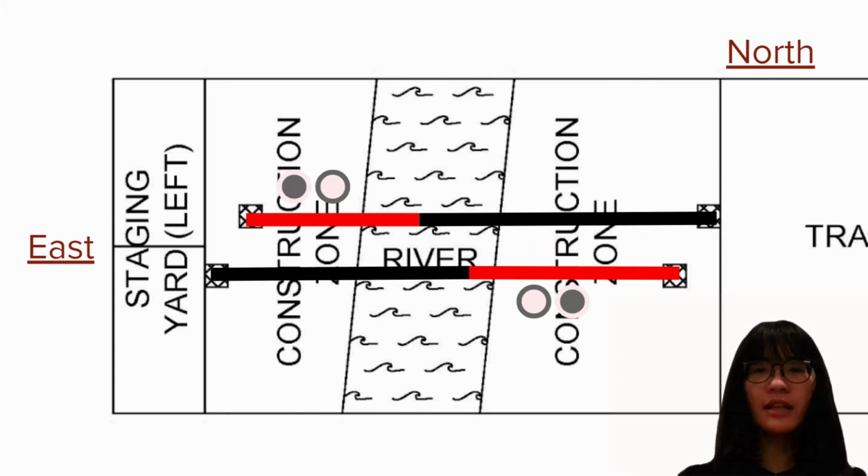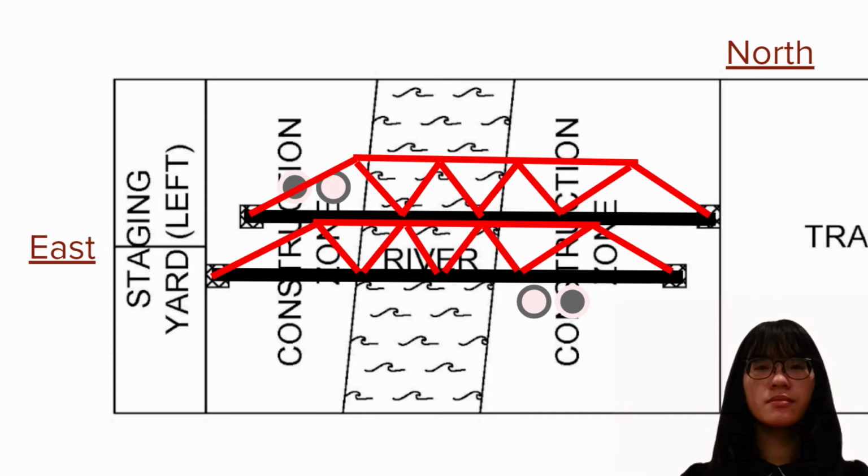Connecting the stringers together is expected to take a short amount of time because of the boltless dovetail connection between space frame members, which allows space frame members to remain stable on their own without bolting through first.